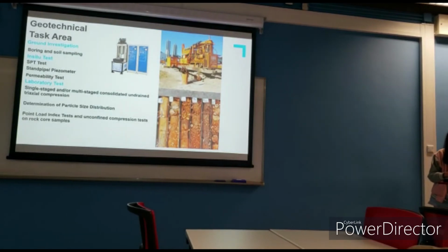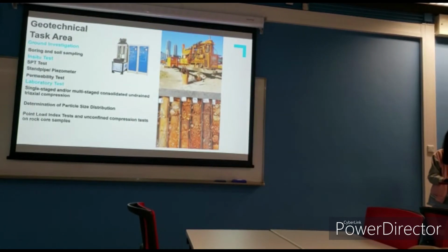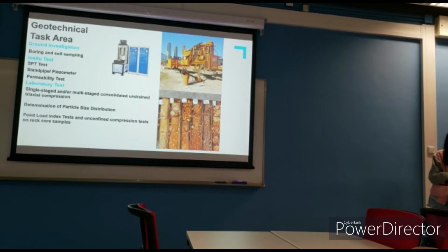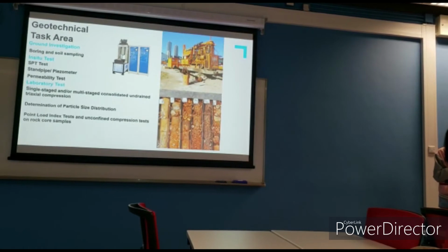In order to get the soil strength and other critical design parameters for the foundation works, we should carry out laboratory tests on the soil samples, including a single-stage or multi-stage triaxial test, determining particle size distribution, or a point load test to verify the rock and determine the soil or rock strength for the design purpose.